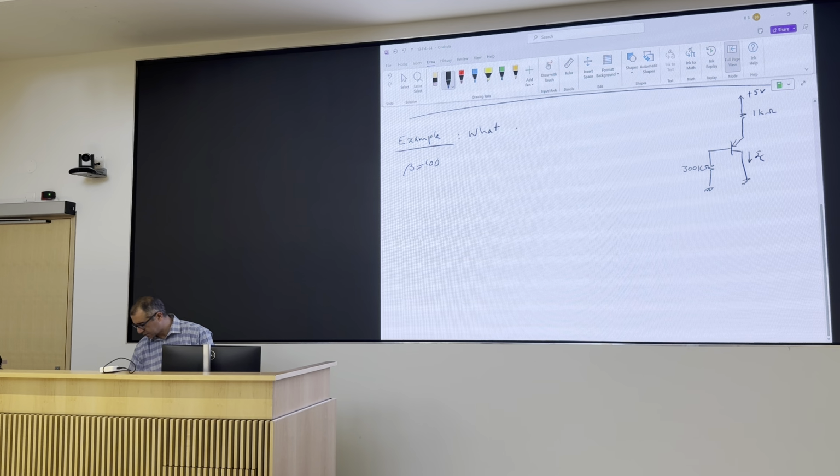But you have this other variable. So let's say you choose some value here. You say, I'm going to bias my transistor at that current. Some VBE gives me some IC. And if you set the value of base-emitter source to be that much, and change VCE, then ideally what you expect to see is this.